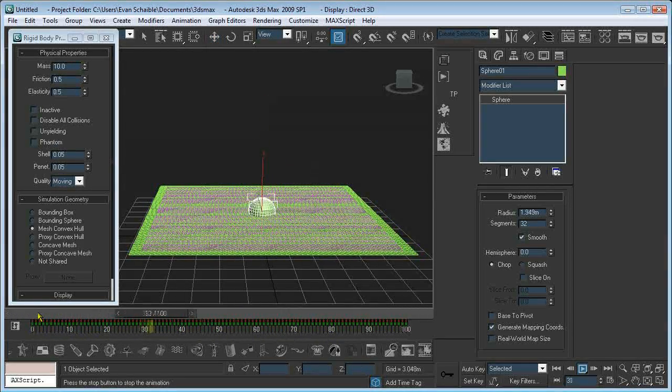And this is pretty equivalent to what RealWave does in RealFlow. Pretty close to the same concepts. So you can see it looks pretty realistic, and it sinks down and pops back up. We don't get any splashes because that's a whole other tutorial, a whole other system in and of itself. But it looks pretty nice as we have it right now. The reason it sinks down and bounces up so much is because our mass setting is about 10 times higher than the density setting of our water.